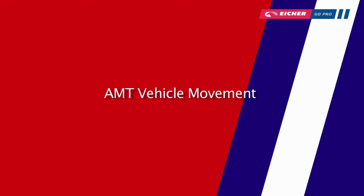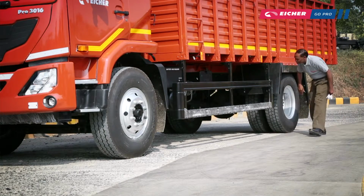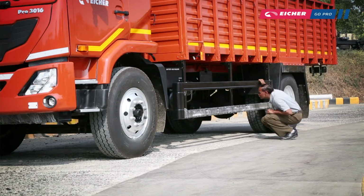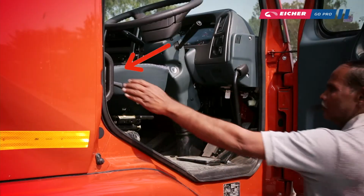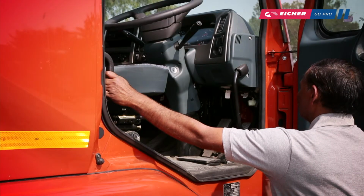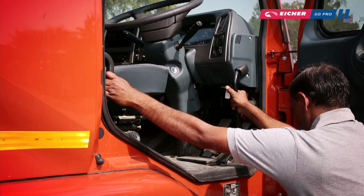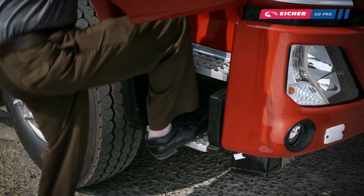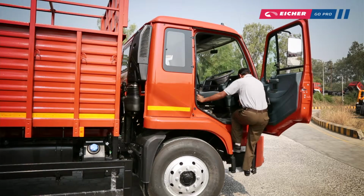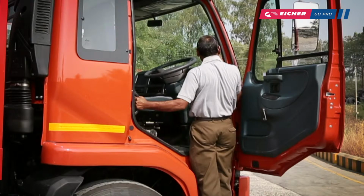AMT vehicle movement. Once you have completed inspection of the vehicle, get into the vehicle. Open the door and hold the rear handle behind the door opening with your left hand. Then hold either the lower or upper handle with your right hand. Place your right foot on the first step. Bring your left foot to the second step, followed by the right foot to the same step.